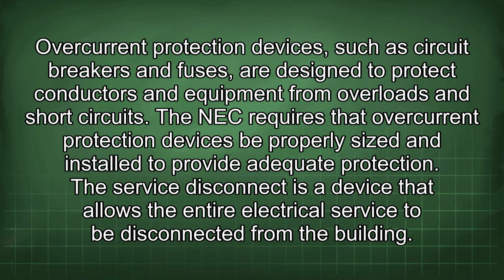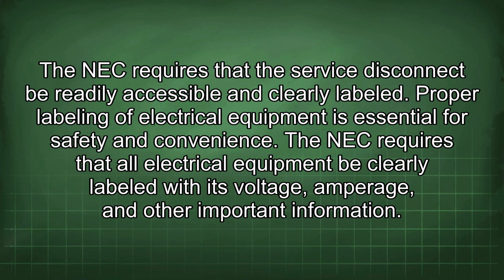Overcurrent protection devices, such as circuit breakers and fuses, are designed to protect conductors and equipment from overloads and short circuits. The NEC requires that overcurrent protection devices be properly sized and installed to provide adequate protection. The service disconnect is a device that allows the entire electrical service to be disconnected from the building. The NEC requires that the service disconnect be readily accessible and clearly labeled.